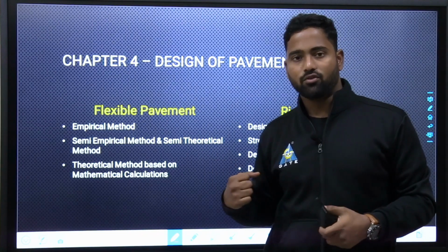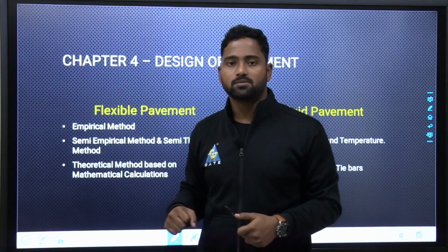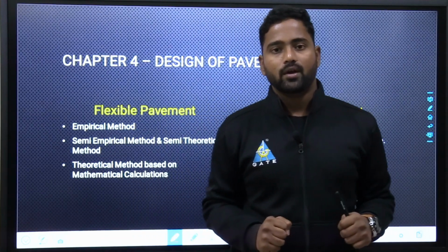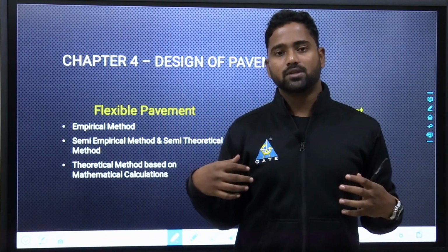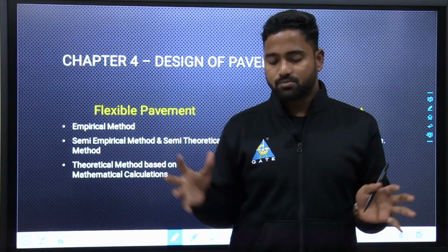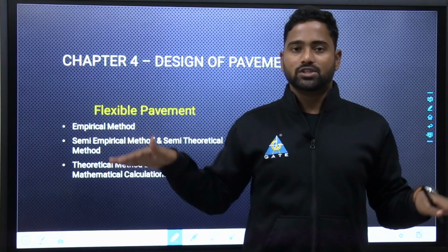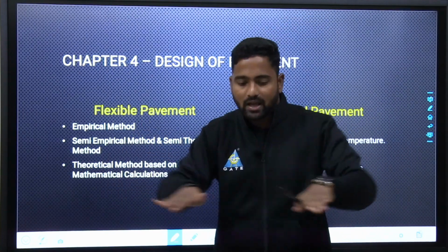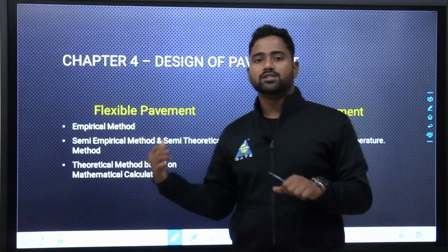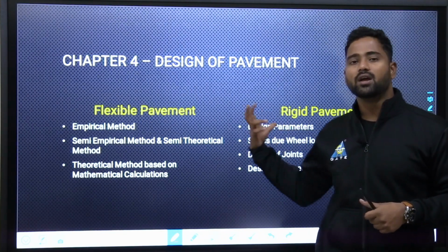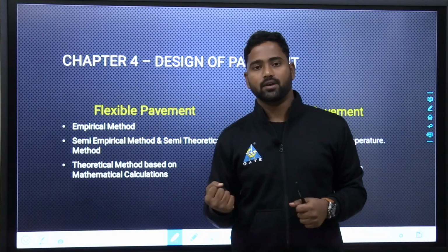That is rigid pavement. Flexible pavement is the normal construction of a bituminous road. There are other types of pavements also, like cement pavement with a bituminous cover on top. Generally, flexible pavement is more elastic, whereas rigid pavement, as the name itself says, is very rigid. It shows brittle behavior, whereas flexible pavement shows ductile behavior.